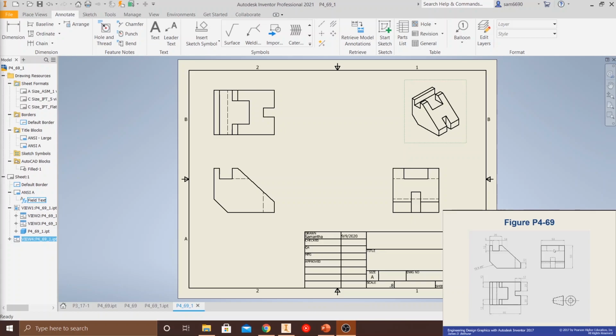But if you turn it around and look at our right side view, you can now see that these lines right here are now full lines, whereas the ones that used to be full lines are now dotted lines. That's because looking from the right hand side, you're not going to be able to see these dotted lines.